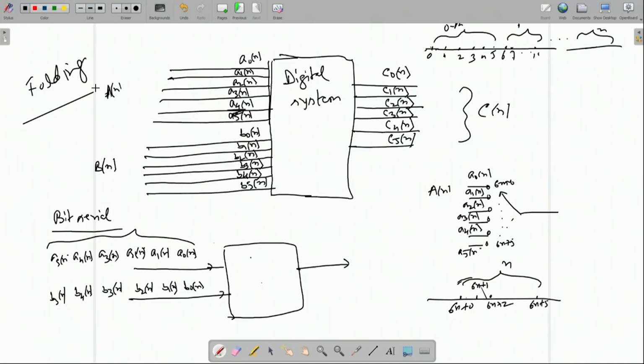If I unfold this by a factor 6, all the 6 data, they will be made as though they are coming out of a buffer, they will be coming parallelly. There will be 6 parallel lines like this for A, 6 parallel lines like B, hardware inside also, if there are some DFG and all that, all nodes will be copied 6 times and the original structure will come up. So, from bit serial you can go to word serial by unfolding.